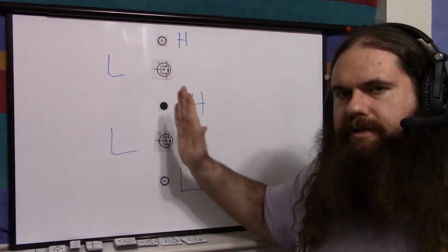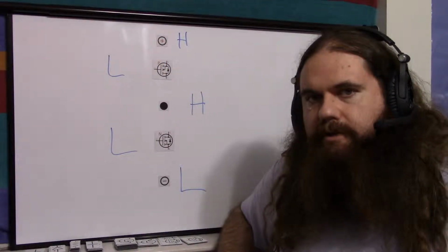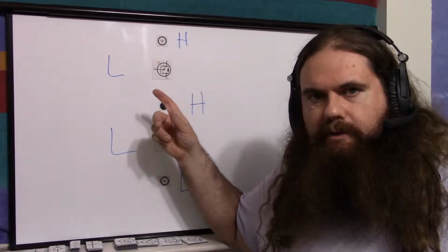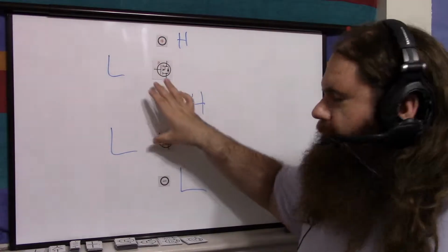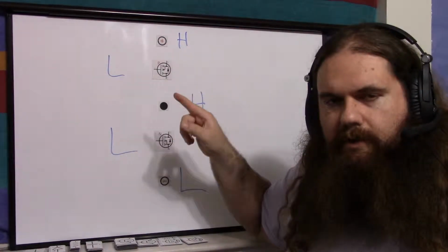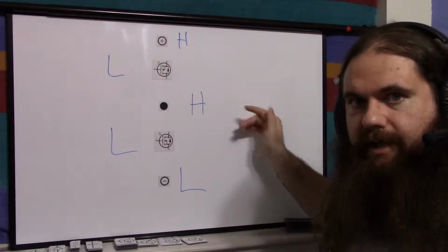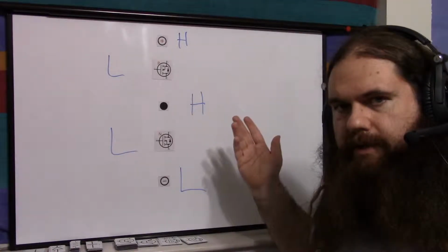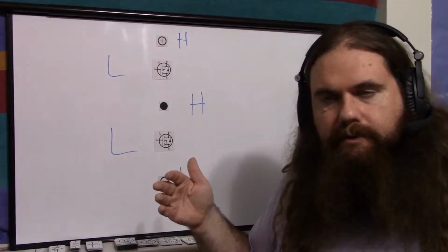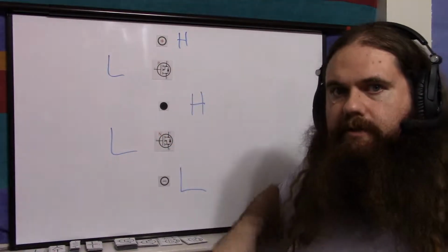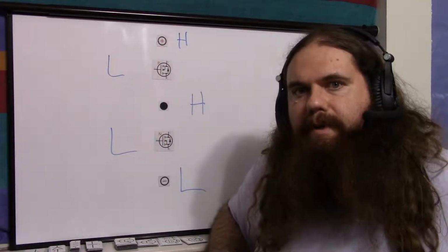There's no constant drain. The gates take current when they charge and discharge. I suppose only when they charge to a higher voltage, really, because when they discharge, they're just dumping what was already in there. So they use current when they charge to a higher voltage, and they use current if there's a load out, so the next gates would use current when they charge and such. Or if there's, finally, something being driven, it'll be the normal load current. But nothing idle. When they're not switching, when there's no load, there's nothing. And so they're super power efficient.